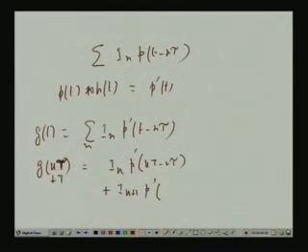It was triggered at k tau and I am sampling at t further to the right. So, k tau plus t, and then k plus 1 tau plus t minus n tau, and so on and so forth. These terms will not be 0 because zero forcing has been demolished. As a result, you will get a combination: I k times some constant plus I k plus 1 times some constant, I k minus 1 times some constant, and so on. Those constants are coming from p prime t, and p prime t is what? Convolution between the transmitted pulse and the channel impulse response.